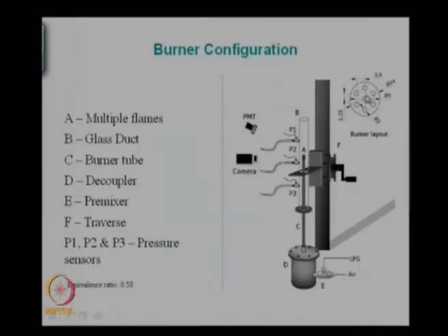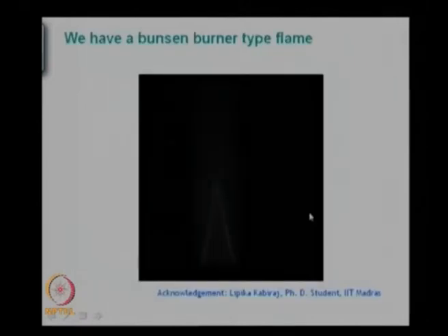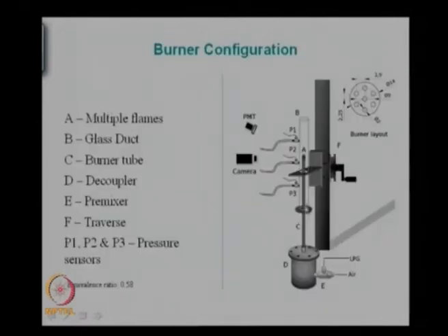with flames standing at each of these holes, and then you put a tube around. You can have a tube which has an open end or a closed end. If there is an open end, there will be draft, and if there is a closed end, there will be no draft, but either way you can simulate a closed end or open end, whichever you want. You can make the pressure measurements with microphones, and you can use a high speed camera to do imaging or a regular camera to get a video, and we can get the chemiluminescence imaging with a photomultiplier tube